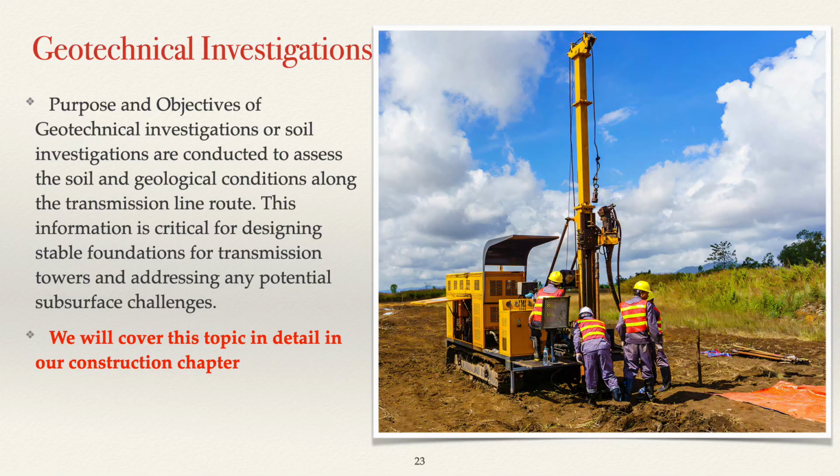Soil sampling. Samples are collected at proposed tower locations, usually through boreholes drilled at various depths. These samples provide insight into soil composition, density, and moisture content. In situ testing. Tests such as the Standard Penetration Test, SPT, and Dynamic Cone Penetration Test, DCPT, are conducted on site to evaluate soil strength and resistance. These tests help determine bearing capacity and other soil properties directly at the location.